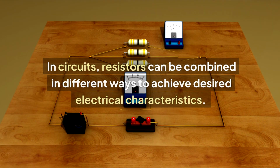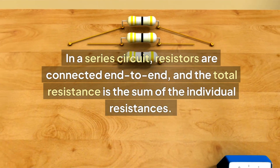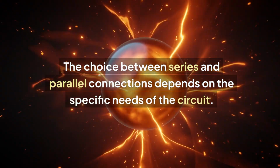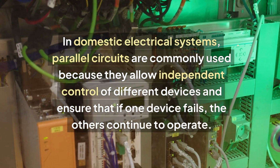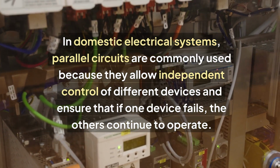In circuits, resistors can be combined in different ways to achieve desired electrical characteristics. Series and parallel are two basic methods of connecting resistors. In a series circuit, resistors are connected end to end, and the total resistance is the sum of the individual resistances. In a parallel circuit, resistors are connected across the same 2 points, and the total resistance is lower than the resistance of any single resistor. The choice between series and parallel connections depends on the specific needs of the circuit. In domestic electrical systems, parallel circuits are commonly used because they allow independent control of different devices and ensure that if one device fails, the others continue to operate.